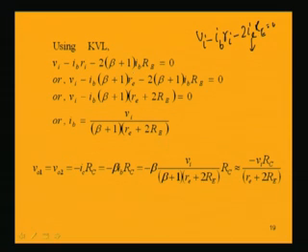So, simplifying it, we get Vi minus Ib into beta plus 1, we can take common. What we are left with is small re plus 2 times of capital RE. Here we are representing Ri by beta plus 1 re. After that we are taking common beta plus 1 re into Ib, that is common.